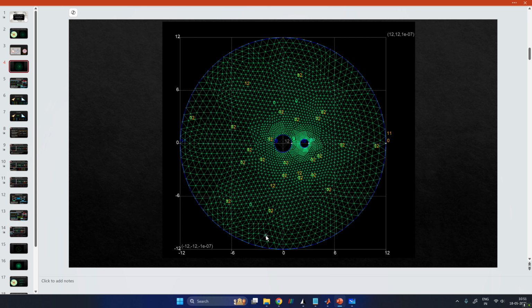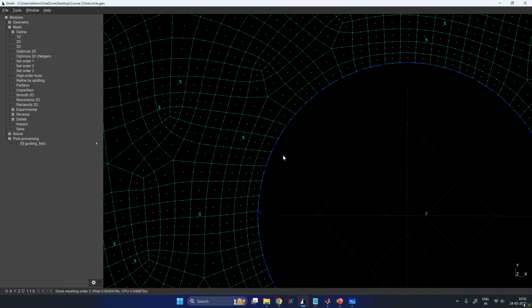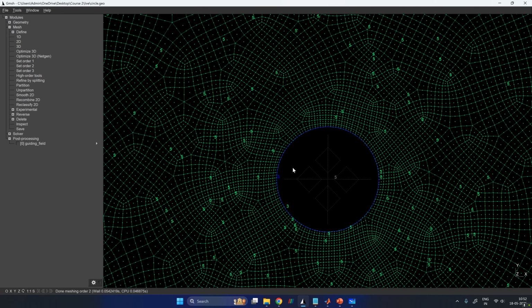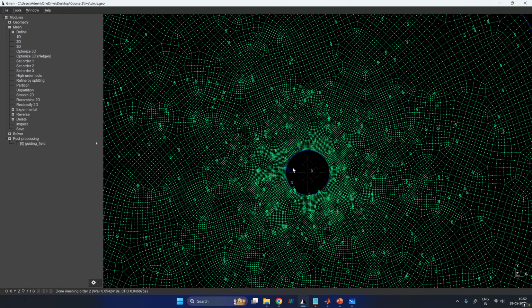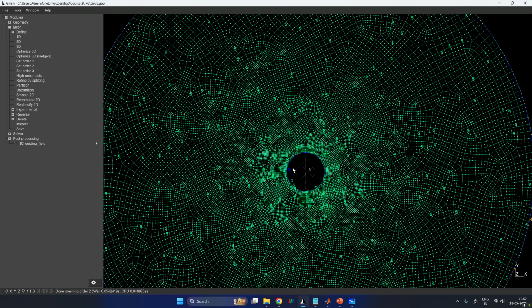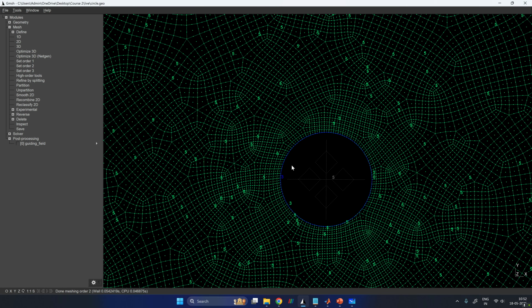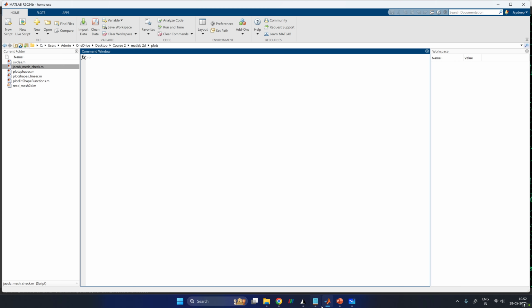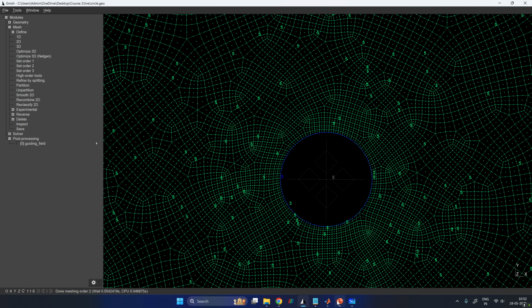So let's try to understand first the triangle and quad elements. Let me also show you a quad mesh here. You can construct it very easily in Gmsh, and I think most of the software started off with triangles because triangles are the easiest. They are easy to refine and easy to build for complex geometries. You could even write a simple code yourself in MATLAB for meshing triangles. They are the simplest of the elements and also very cheap to model or code with.